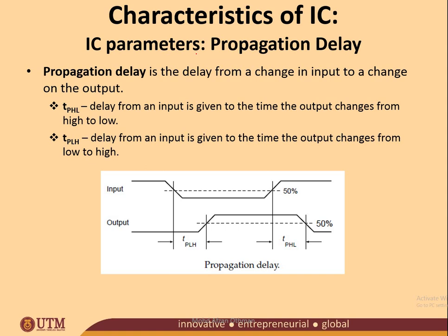chips. You need to consider all of these propagation delays from each chip. There is a lot of chips in a circuit, and each chip has its own propagation delay. You need to take care of this propagation delay, otherwise the design will be out of spec. For example, if you expect from chip 1 to chip 2 a propagation delay of around 1 millisecond.